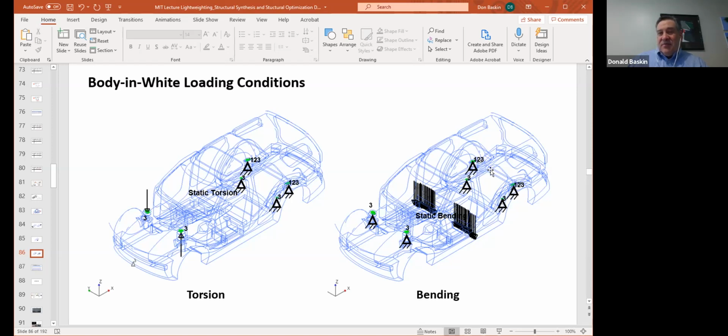In some cars, maybe the customers aren't that particular, or the company doesn't have the money to do things the best they can, suspension mounting points are left in single shear. But this all goes into the structural efficiency of the mounting. If you want that mounting point to be as stiff and strong as possible, you can get a stiffer, lighter structure by using double shear than you can with single shear, but you are going to have to pay more money for it almost always.